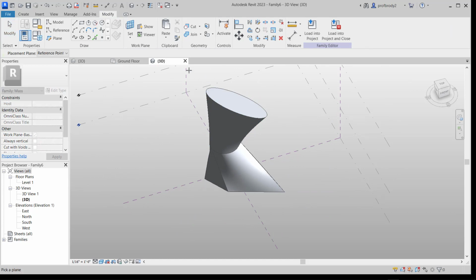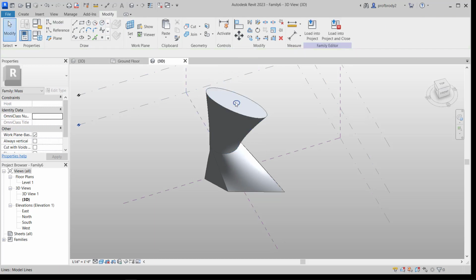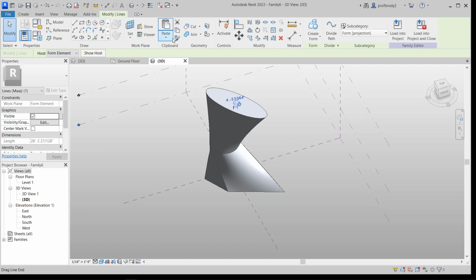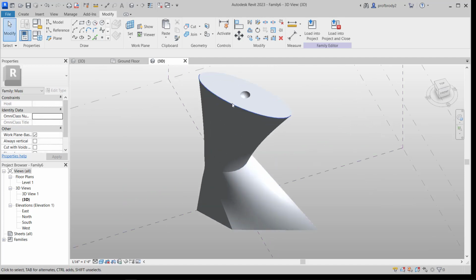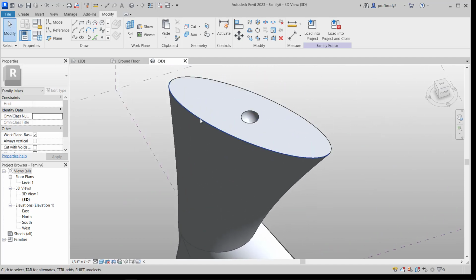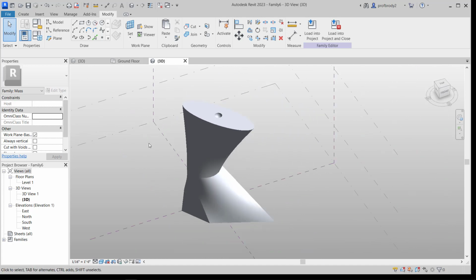The other thing is that you can set the reference plane to be really any flat plane. So I could choose this top plane here, and I could draw some more shapes onto that. And again, just start creating different extrusions, which is kind of the basic form. But I could also create a void form. And like we saw before, it's asking me, do I want this to be a round or a tube shape? If I chose the round shape, and this time, to get kind of a little weird divot there.